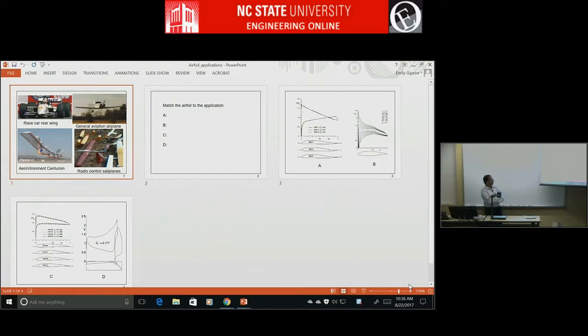Okay, can we nail one application down right away? Yeah, of course. D is the race car wing, obviously, because I just talked about this, right? There's the constraint box, and this is just when we were designing it for that particular racing application. Every racing application has got a different constraint. Anyway, so this is a 2-element airfoil. It's got to generate high lift, but upside down. So high downforce. Here I've plotted it as in the aeronautical way.